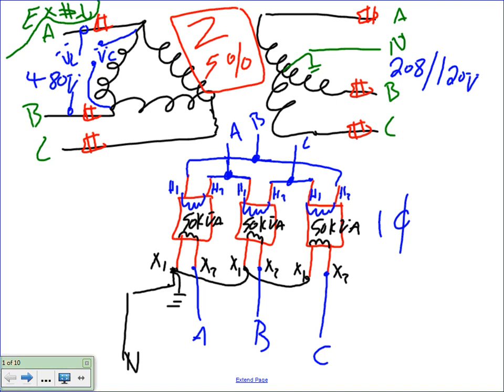Okay, on the secondary, I decided to use 208Y/120, and the impedance of this transformer, Z is the impedance, is 5%. The impedance of this transformer is 5%. Can I have a thumbs up that we know exactly what we're looking at here? Cool? Okay.